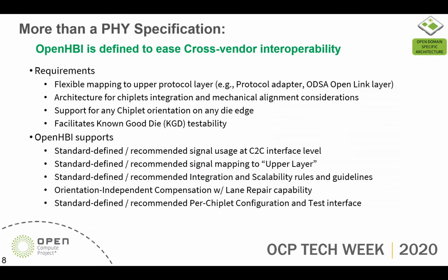Okay. So to build an ecosystem, however, to offer a truly interoperable cross-vendor chiplet ecosystem, we need much more than a die-to-die or chip-to-chip PHY specification. We see the following are required at a minimum. First, the spec must support flexible mapping to the upper protocol layer. Second, it must define an architecture for chiplet integration and mechanical alignment. We cannot just have a whole bunch of chiplets randomly placed along any die edges, and then they won't work together. And also the dimensions have to have some guidelines.